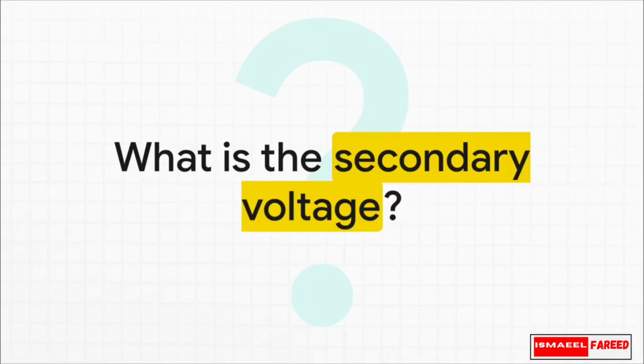All right. Let's put you in the hot seat for some on-the-fly math. An interviewer might easily throw a scenario exactly like this at you to test your fundamentals. Say you have a transformer with 500 turns on the primary side and 100 turns on the secondary side. If the primary voltage is 200 volts, what is the secondary voltage? Did you get it? It's 40 volts. By just applying the basic turns ratio formula, you can quickly see the ratio is 5:1. So that 200 volts scales down perfectly to 40 volts.